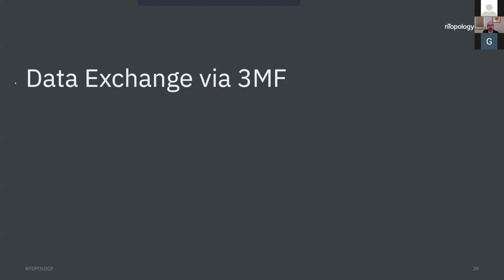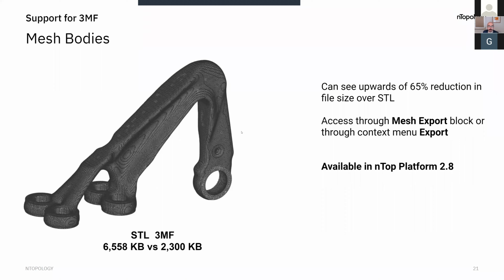All right, so I'll jump back over and let's talk a bit about data exchange. So we've added this new capability within nTop platform to export out 3MF files. Now, for those of you that are familiar with mesh-based formats, we know that STL is kind of the format of choice for a lot of folks, particularly in additive manufacturing, but that format has a lot of problems. And so we've decided to adopt the 3MF file format standard.